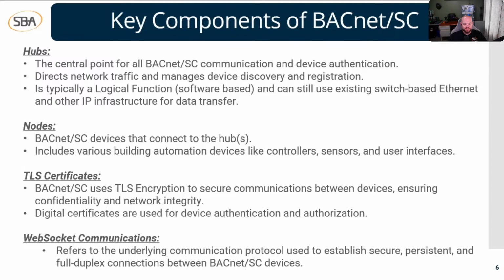So this is what I was saying in that previous slide. BACnet IP controllers and devices are still going to be compatible with BACnet SC. So great thing here. But the big takeaway for the hubs is to remember that it's a logical function. It's software based. It's not a physical switch or anything like you would think of with a BACnet IP system.